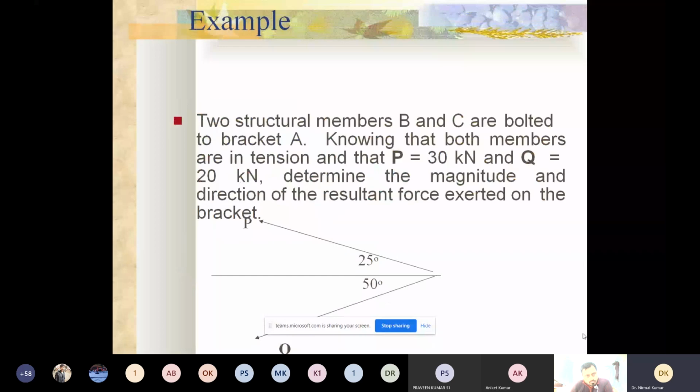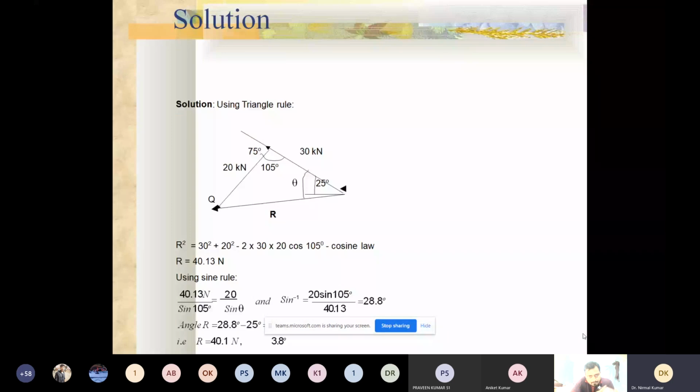आप इस फिगर को देखिए, यह 50 डिग्री पर इंक्लाइंड है, तो इस पॉलीगन्स को, यह 20 न्यूटन फोर्स है और एक 30 न्यूटन का है. यस, इसी पैरेलल डायरेक्शंस में you draw the polygons and you will get this triangle by drawing the polygons. Closed polygons you will get because we are discussing the equilibrium. The equilibrium जब भी डिस्कस करेंगे they will form the polygons, closed polygons. और angle geometrically we are able to find this 105 degree, 25 degree.